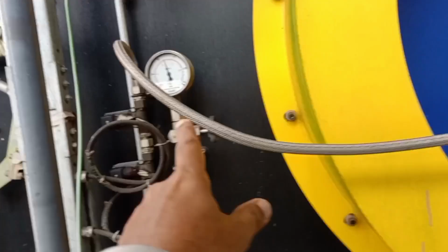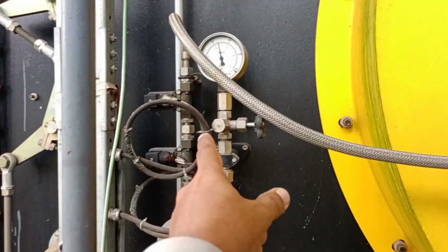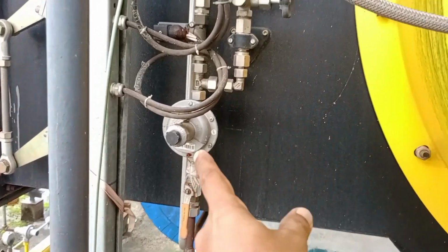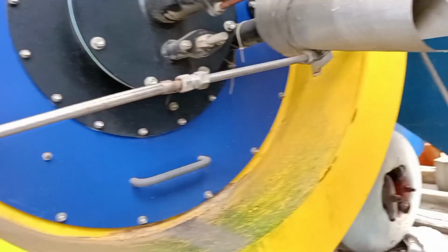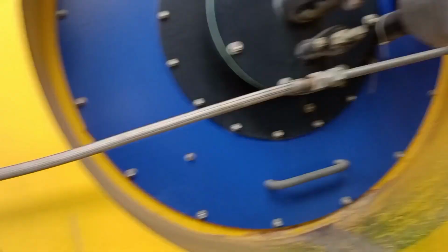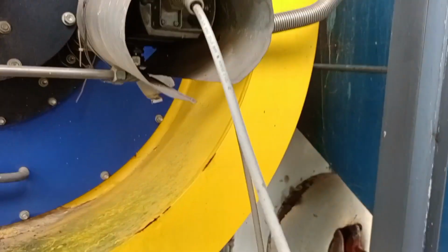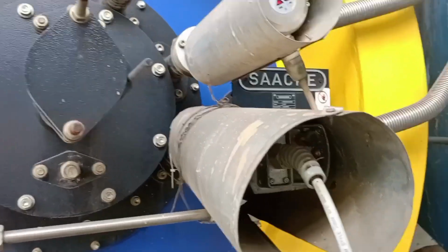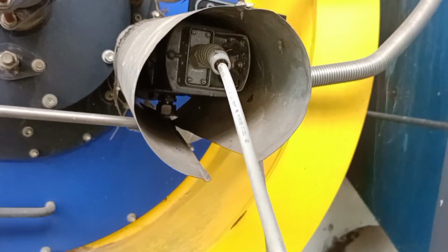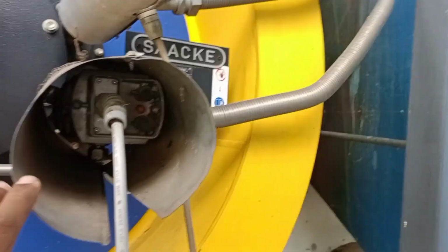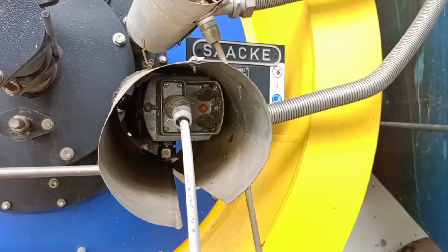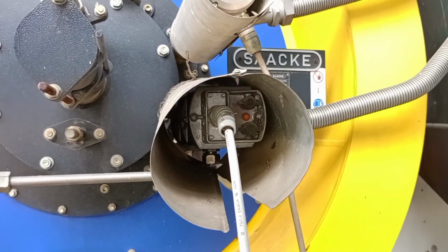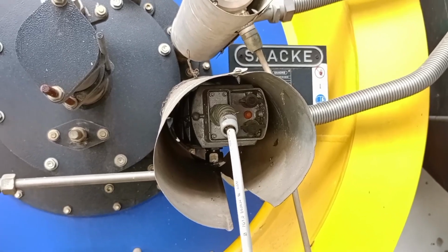At this time, here is a solenoid valve and also a gas regulator. A small amount of gas passes through this line to the igniter, and also here is the air line, and this is the electrical signal line. Through this electrical supply line, the igniter has electrodes, negative and positive. There is a high voltage plate. Its supply voltage is 220 volt AC and output voltage is likely 9000 volt.